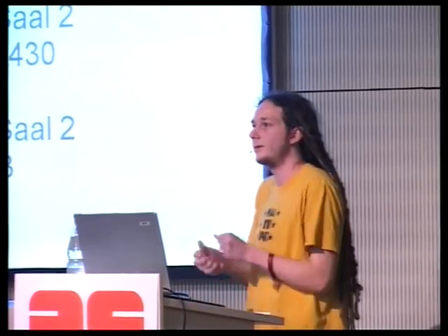So I printed out the disassembly of the code. And then for a couple of days I went through and I annotated the different pieces of it. The lecture that I'll be giving on the 29th in Sal 2 on repurposing the EZ430 describes the tools that I used for this. I've got a Perl script called msp430 static that lets me identify every function that contains access or code that writes to a particular I/O port.